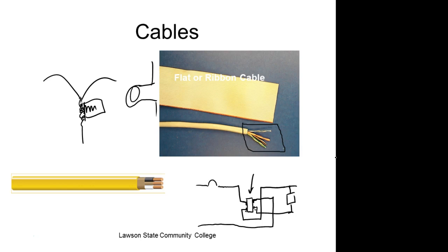In a communication system, what we're trying to do is get the maximum transfer between our transmitter and our receiver. In a communication system, you get that when all the impedances in your circuit match. So instead of arbitrarily choosing them, we actually set these cables to have a certain impedance at a certain frequency.